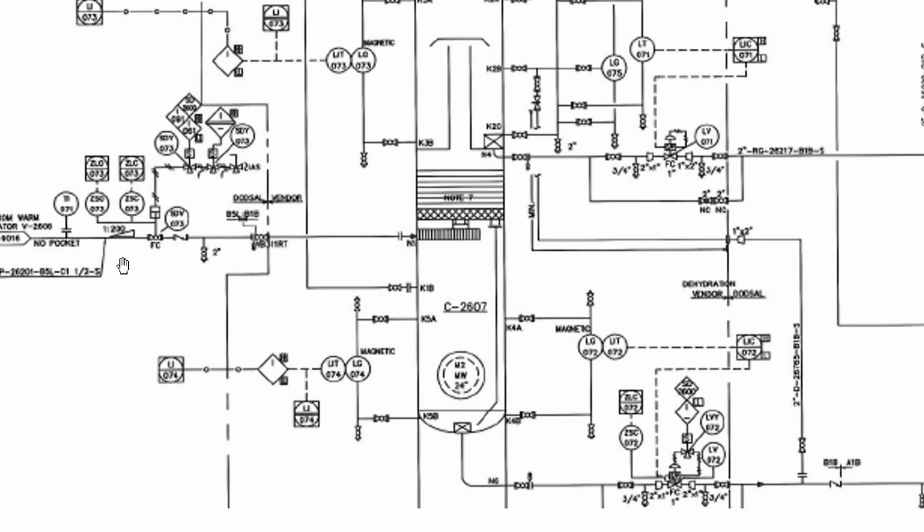The bottom part, where the sour gas line is entering, is an inlet knockout drum. See, the inlet knockout drum is there. The inlet knockout drum is a vessel where any liquid and other contaminants can be collected, and there is an inlet device. The inlet device we have discussed in various locations, like the separator.